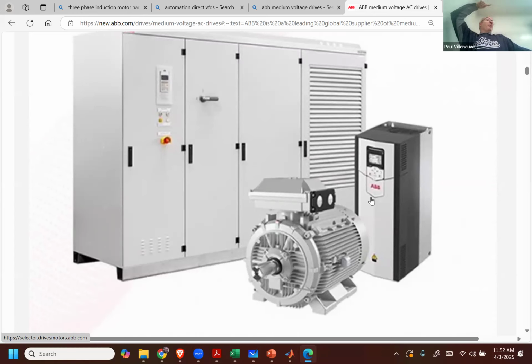But remember how we start gas turbines, right? We can't start synchronous machines across the line. If you go just down the road, there's also the same thing in Westbrook. If you want to start those gas turbines, you can't just light the fire and let them go, they'll burn. So they've got to be started. And those are 150 megawatt generators. So conceptually, you could be pulling 150 megawatts of power through that.